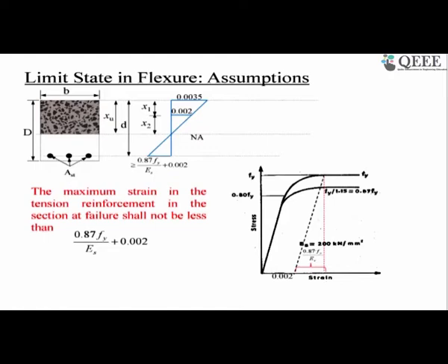The next assumption again comes directly from the idealized stress-strain behavior of steel. Somebody asked that if we know the strain, how to determine the stress. Yes, we discussed that, but recall that discussion as well. You see, this is the 0.2% proof stress, so this is your yield stress. Now what will be the strain at your yield stress at the characteristic load? This portion is linear, and the slope of this curve is your Young's modulus. So this distance will be your stress divided by Young's modulus.